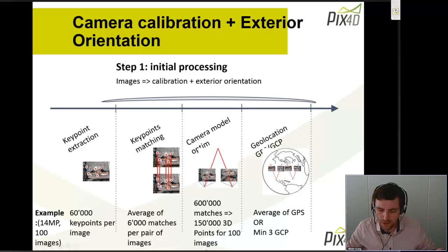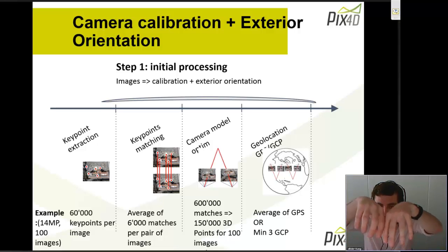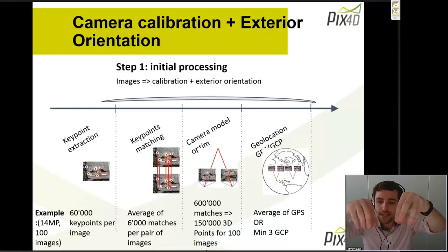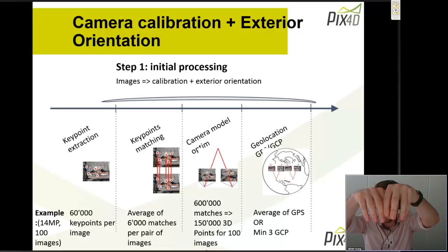After finding matches, there could be many wrong matches and many correct matches. The software is going to try to orient the cameras in 3D with respect to each other by using the matches and by using an initial guess of how the perspective is working in this camera. It will do it in an iterative way. By that I mean that it will start first with 2 cameras to try to put them together.